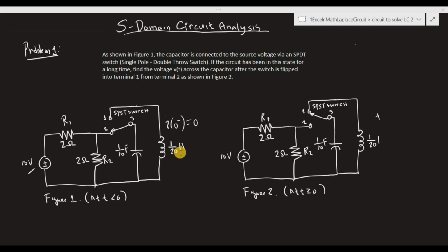In this video, we're going to analyze an LC circuit and do our analysis in the S domain. My objective is to provide you with some vital insights about S domain analysis. The advantage of this approach is that we don't need to formulate our solution in terms of differential equations, and this method also expedites the computation because the initial conditions are included into the circuit in the S domain.